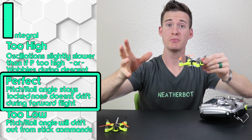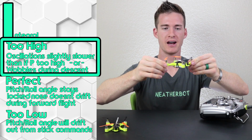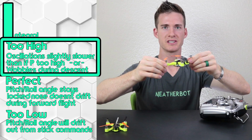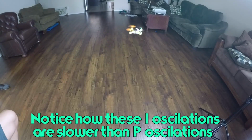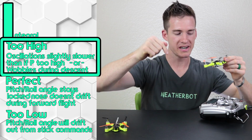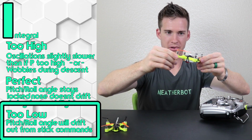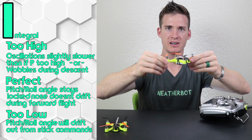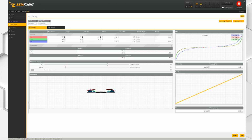And then if you get too much I, you're going to start getting those crazy oscillations back while it's hovering. So if you get oscillations, bring I down, and if you're getting the little drifts when you give a little bit of input and the nose wants to come up or whatever, then you need to give more I and bring I up.